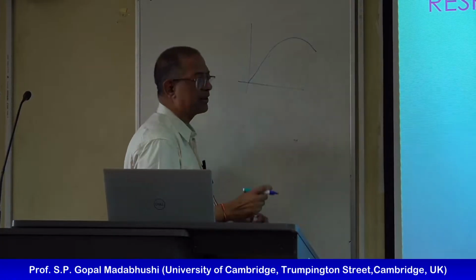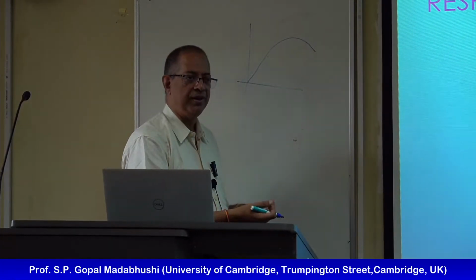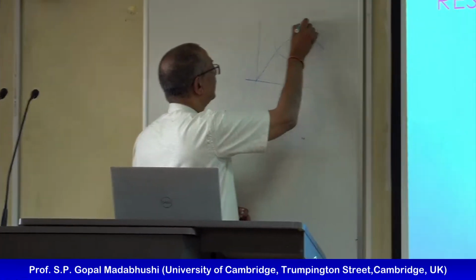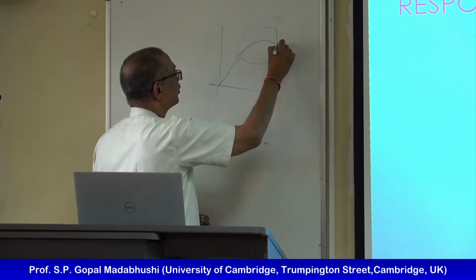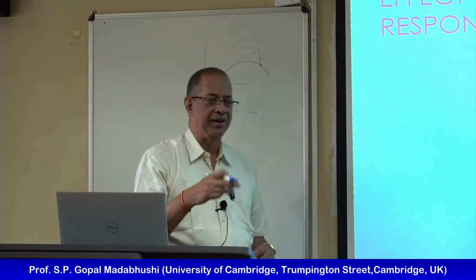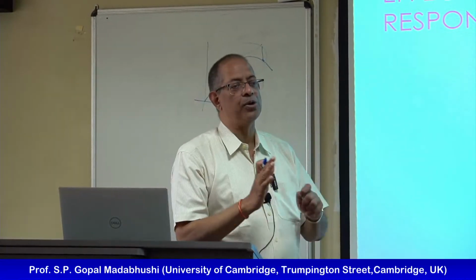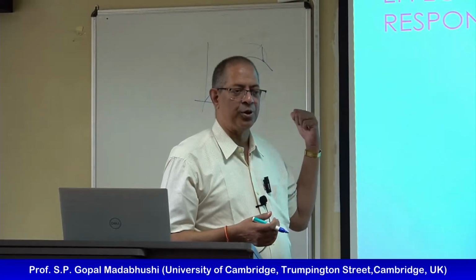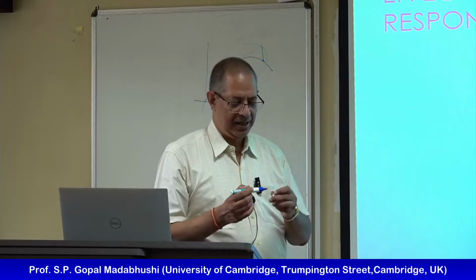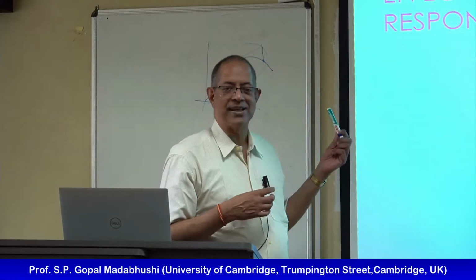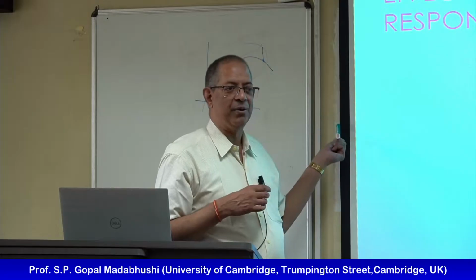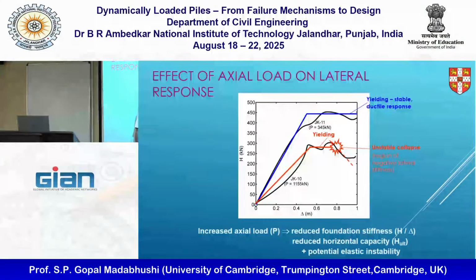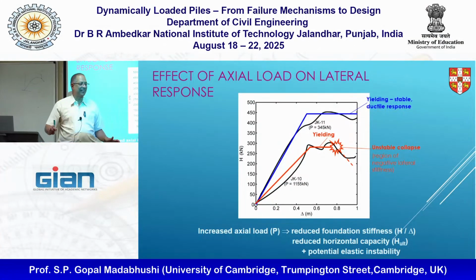If you want to capture that kind of post-buckling behavior, you need to draw a circle around here, draw tangents, and then work your way down here, iteration by iteration, and then you can follow post-buckling deformation behavior of columns. So that's what he has done for the numerical bit, but effectively that is for ego satisfaction. For a practical engineer, once you reach this, as he has drawn here, crash bang, pile dead is about right.